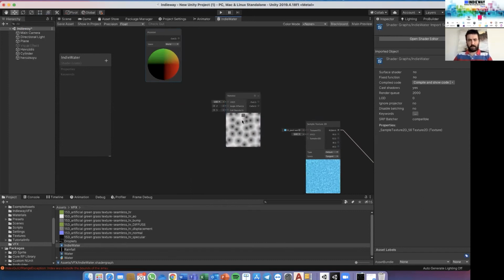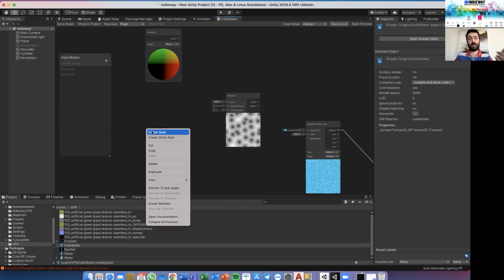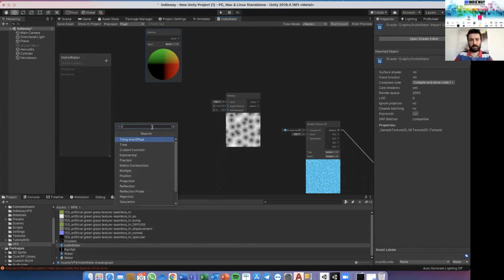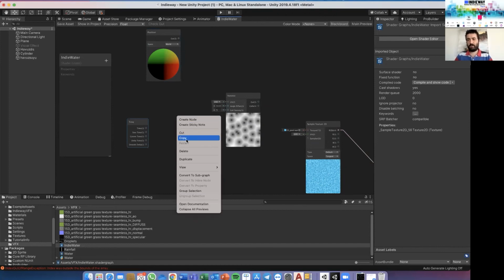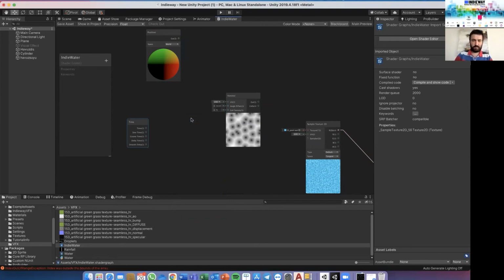I want to exchange the locations of these two. They are moving, you can see, and I want to change the angle of sets here. Actually, it is a time dependent variable. It may be changed in time. To do this, I right click and create new, and then I add a multiply function.